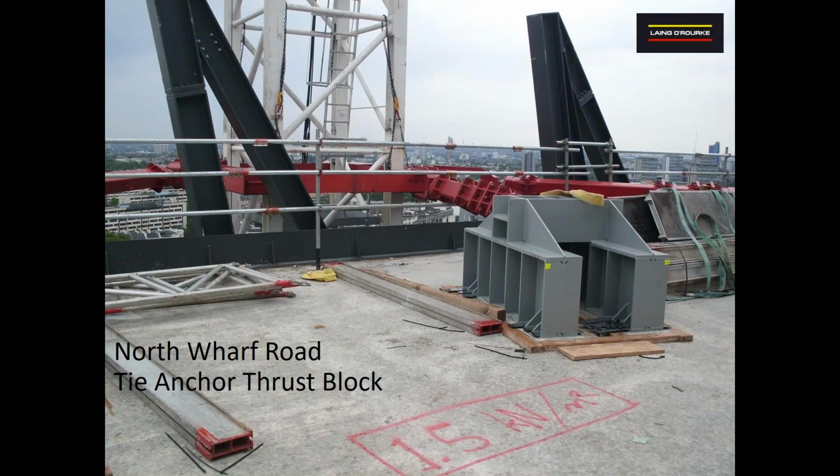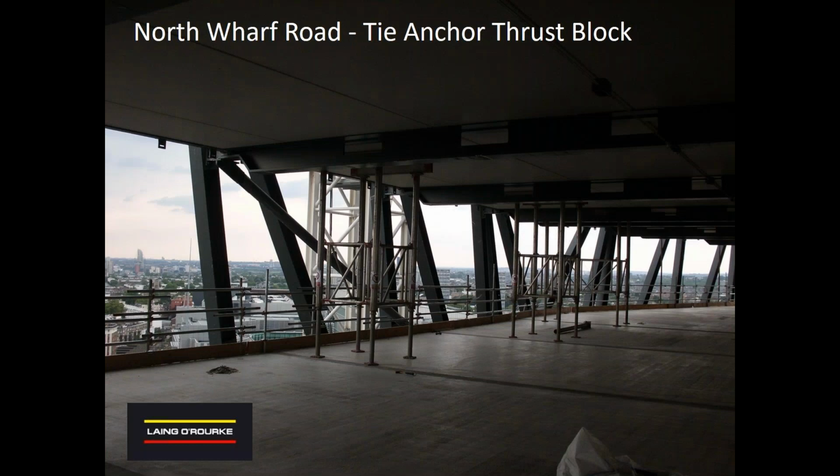Exclusion zones and slab, gas props below the slab. The thrust blocks weigh a reasonable amount in terms of their self-weight, and so just to give the slab a bit of a helping hand in terms of minimising any possible risk of cracking, a bit of deflection, it makes sense to have exclusion zones, to have gas props, back propping, especially as not only have you got the self-weight of the thrust block, you've also got the vertical reactions due to the horizontal load being applied from the ties to the thrust block.